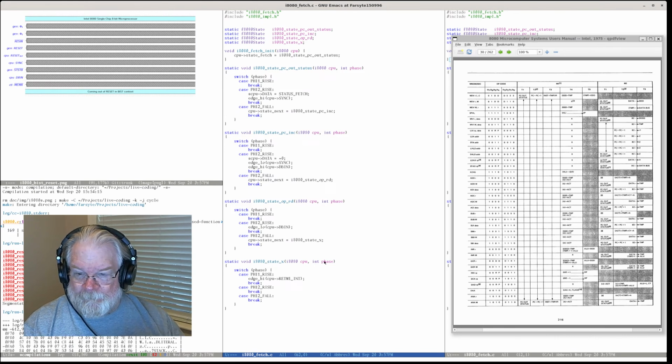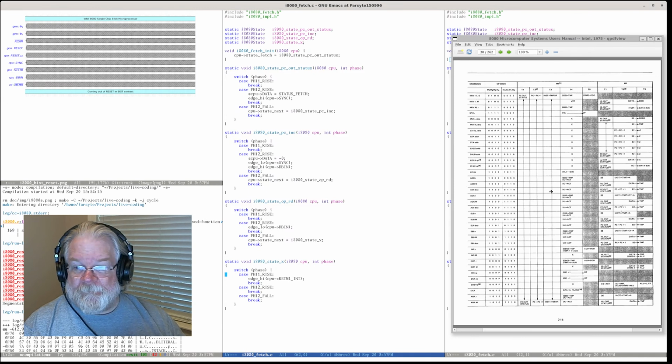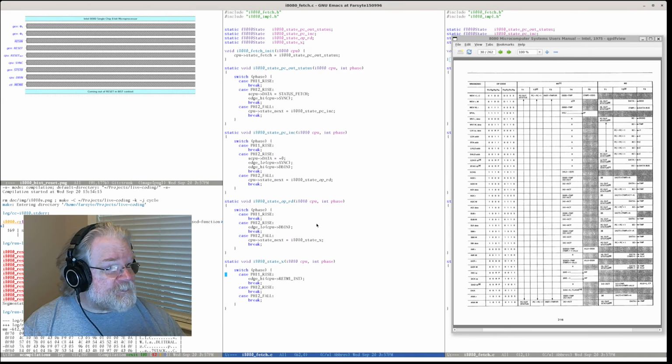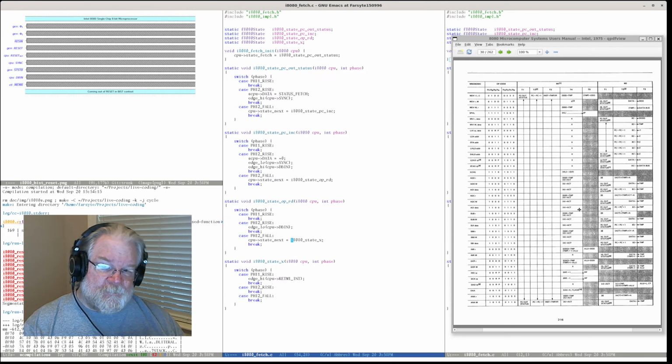So it is likely that if we look at that dispatch table on the right there that I've still got up, once we come out of the T3 cycle here, so this op-RD, which is the T3 cycle, state next isn't just going to be state X. It's going to have to be the proper T4 cycle for the instruction, and almost every instruction is going to be different. And the ones that are the same, if we use distinct functions, then we don't need to later on do the work and then, if this condition is true, do something else.